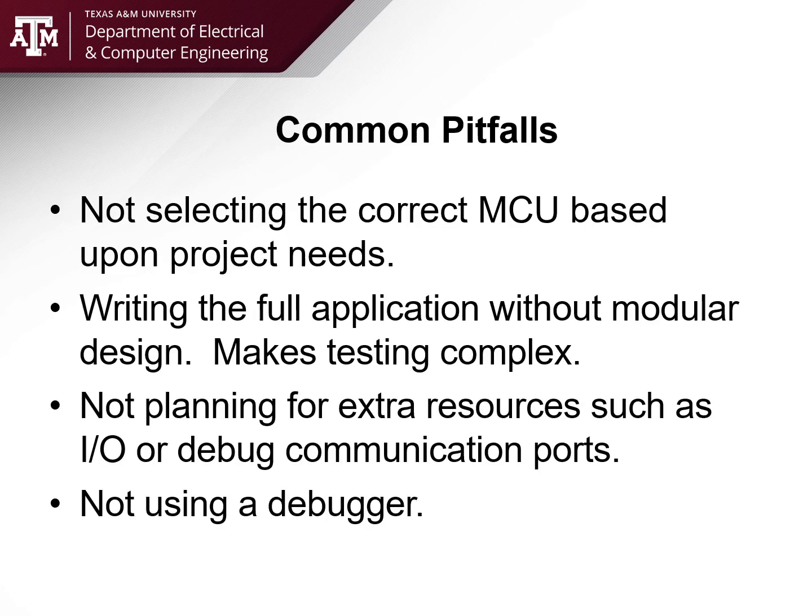So, common pitfalls, we'll just kind of wrap things up here. Not selecting the correct microcontroller based upon project needs, huge. This right here is probably the chief problem that I run into personally as an embedded systems engineer: I will choose the wrong microcontroller based upon the requirements. That's why it's so critical to make sure you have a requirements document for the project you're working on.